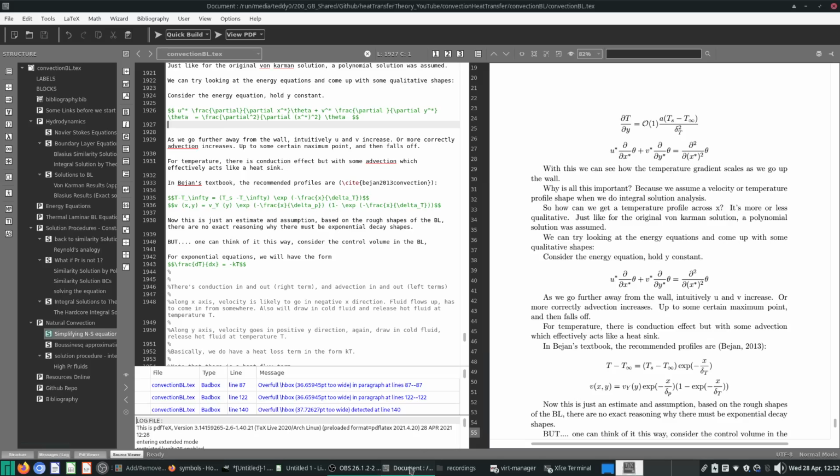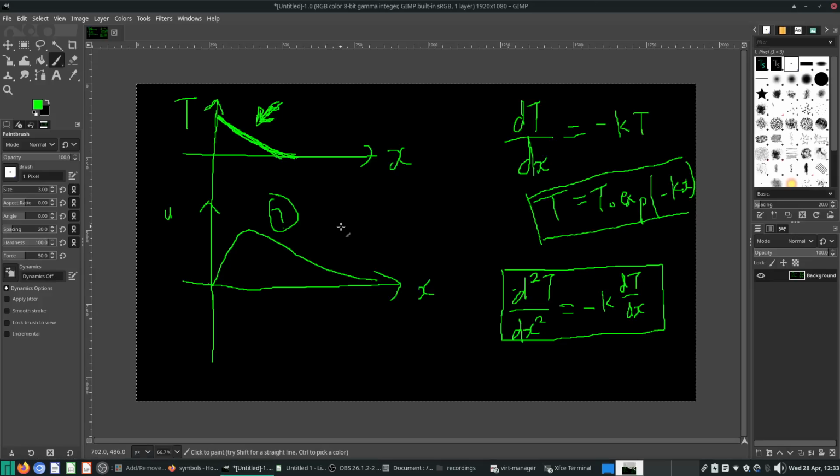Okay, then that gives us a clue as to what this part looks like. It may be a sort of exponential equation. Now, of course, u is negative. Why is u negative? Because if we take a look at this diagram, x goes in the right direction, but likely velocity of fluid will flow from the cold part of the region to the hot part of the region as part of natural convection. So u should always be negative. It should be less than 0, or at least u star should be negative. So from this we can see some sort of rationale for an exponential decay curve.